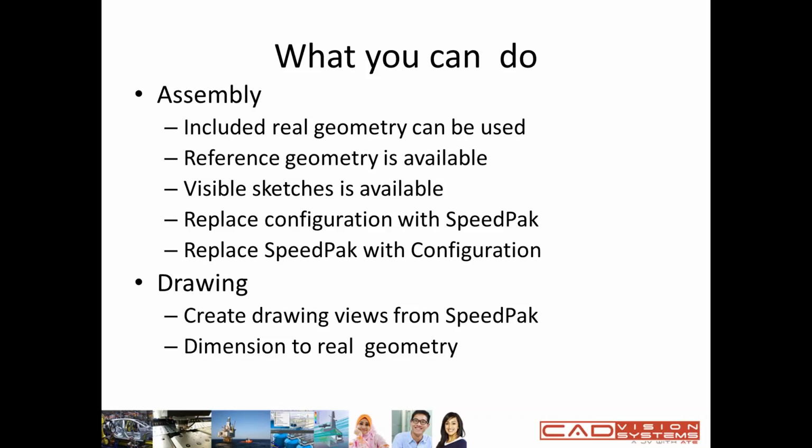Basically, you suppress all the other components that you didn't select. So in a SpeedPak configuration, you only load the information required to maintain reference at the top assembly level. In drawing, you can also create a drawing view from SpeedPak, and dimension to real geometry.